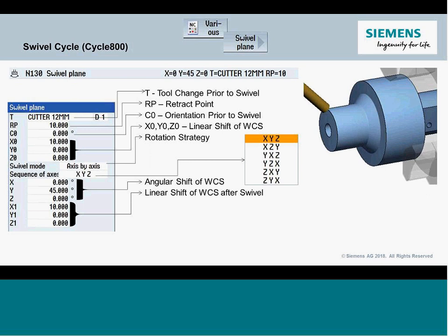There's a couple things that get pulled out of here that you have on the mill side, but pretty much it's almost identical. Tool change, I can retract strategy. Here, this is unique. I can clock or orientate the C position. You would obviously have that in a milling machine, but I would have it on a turn mill. That's where I can spin my part around, just like you've been seeing in the other cycles, where I position my C for that feature.